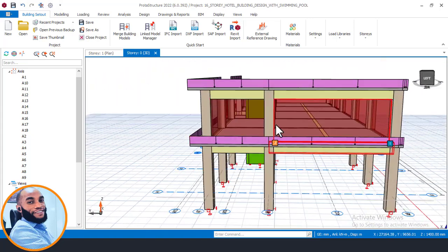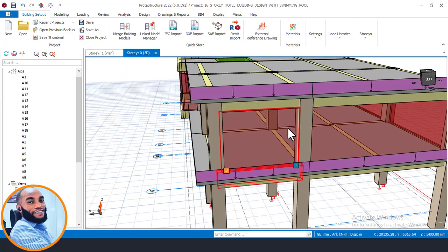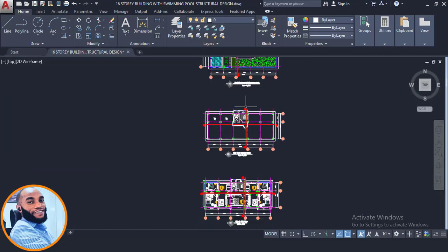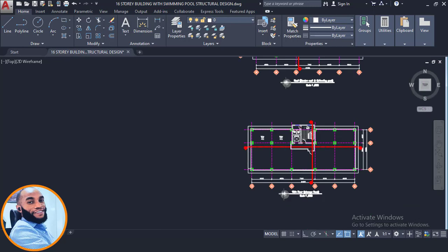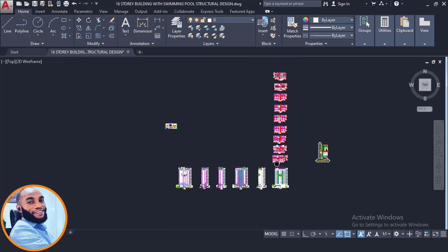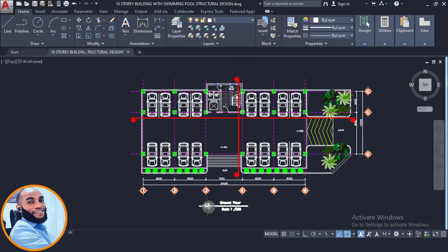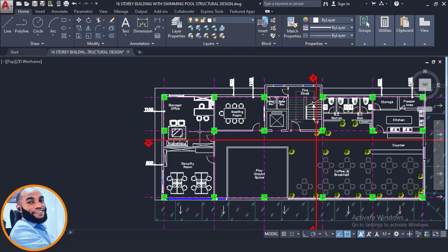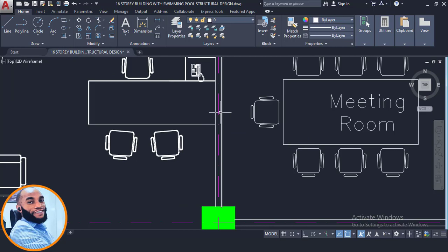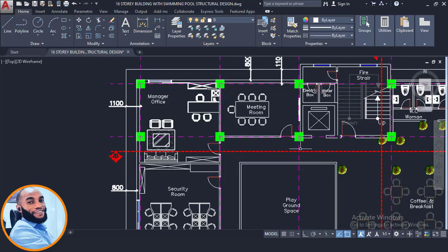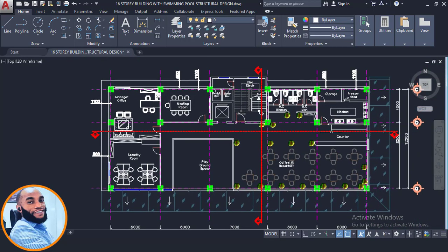All these other internal beams here might use partition walls. Because you can see from our CAD file here, there is no load on the partition walls, which you can also see. Let me see that. You can see that there is not much load here. This is basically not a block wall. This is a partition wall. Okay, so we are not going to add load on that.